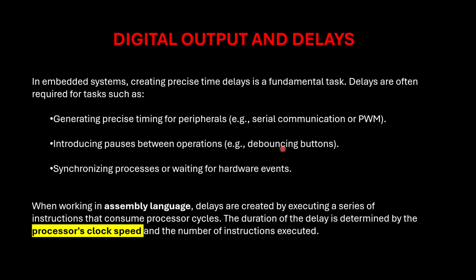If you still are not familiar with the debouncing term, basically it introduces a certain delay before actually triggering the action. Okay, so imagine for example that you press a button, and then that button won't immediately perform whatever it should perform, right? It will wait a certain amount of time and then it will trigger the action. So that is why knowing how to perform delays when creating a debouncing button is important.